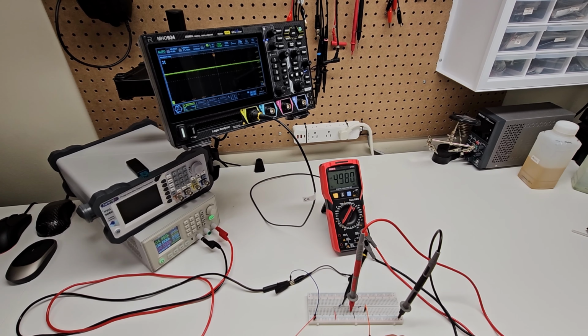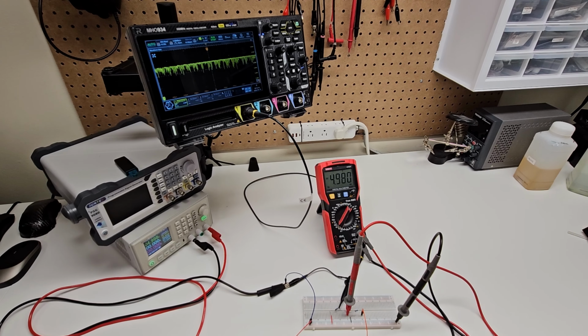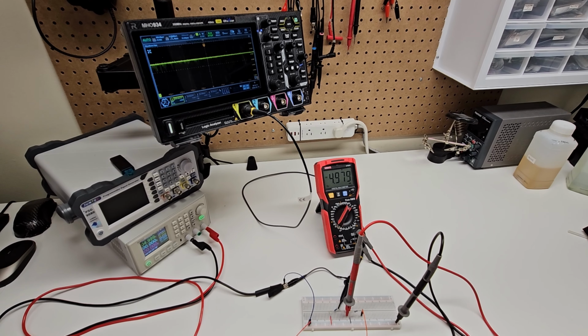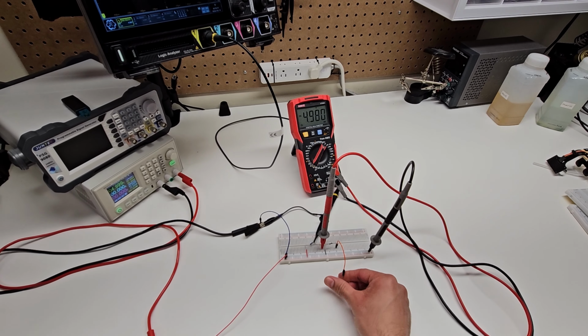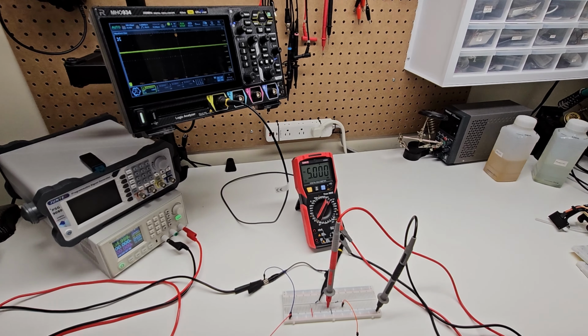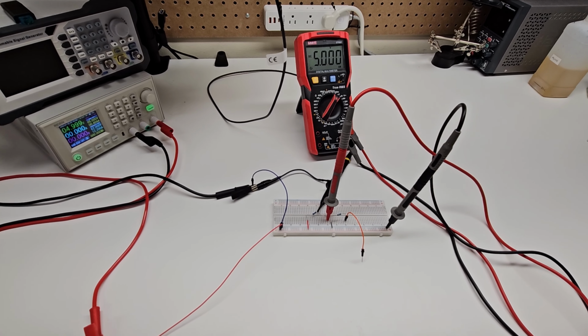So the transistor is partially turning on. That's the reason why the voltage is dropping a tiny bit. So a tiny bit of current is flowing. So this is not good. My hand just touching the wire is enough to do some capacitive coupling. So this is not good. That's why we have a pull down resistor for NPN and a pull up resistor for a PNP.